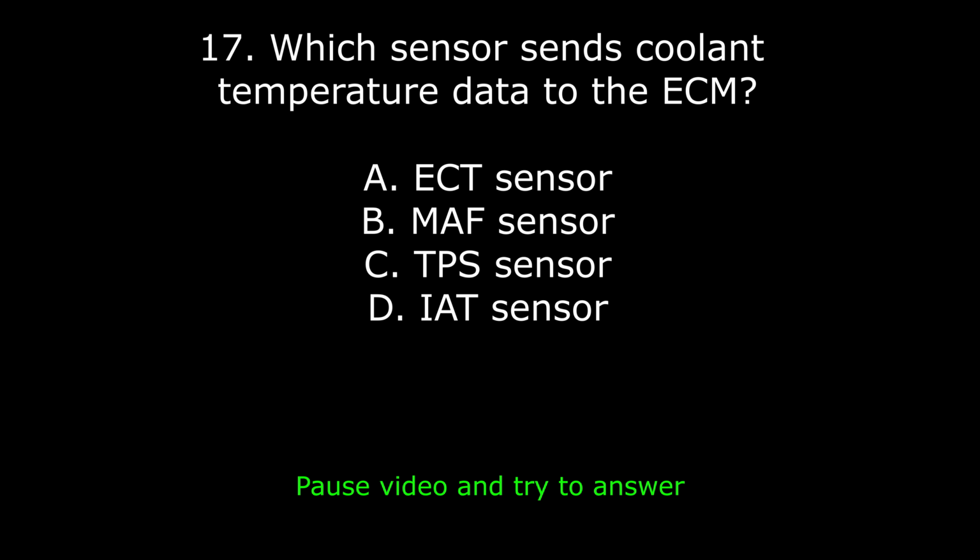28. A vehicle overheats only at highway speed. What is the likely issue? A. Thermostat stuck open. B. Fan clutch failure. C. Airflow blockage or restricted radiator. D. Low coolant. Answer: C. Airflow blockage or restricted radiator. Explanation: at speed, fans aren't needed. Restriction prevents efficient heat dissipation.